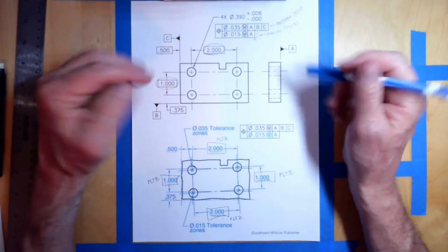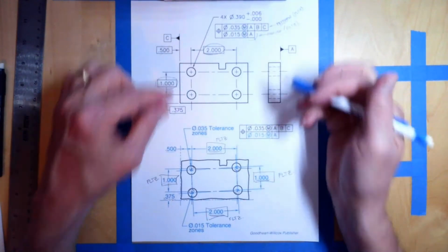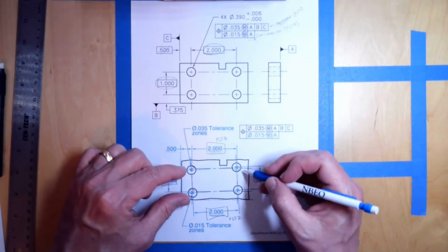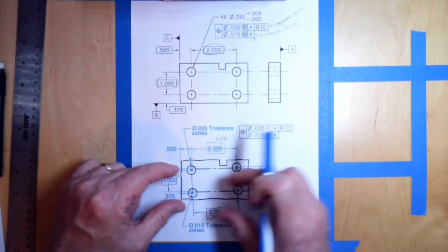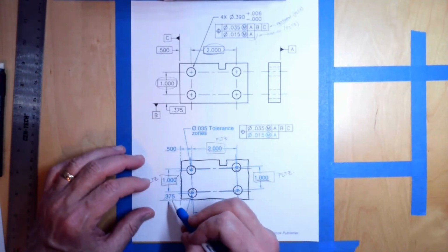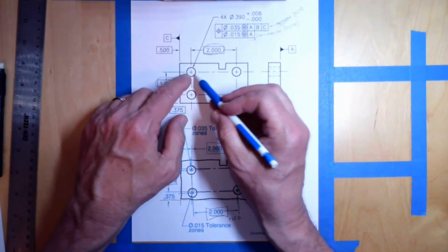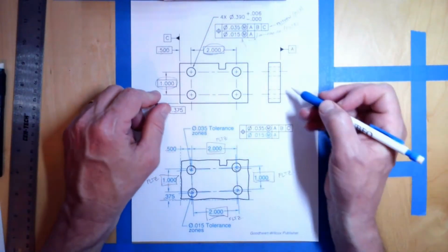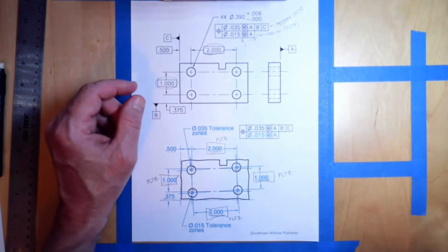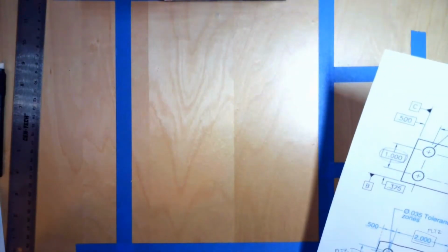We don't want to reject something, right? We don't want to reject a part because the holes are too close or too far away from the sides, when that really doesn't matter. What matters is the location of the holes relative to each other. And that's what the feature locating tolerance zone says. Okay. Now, let's look at